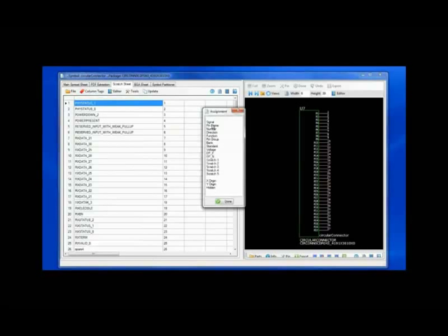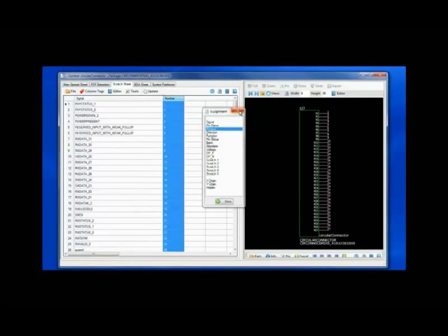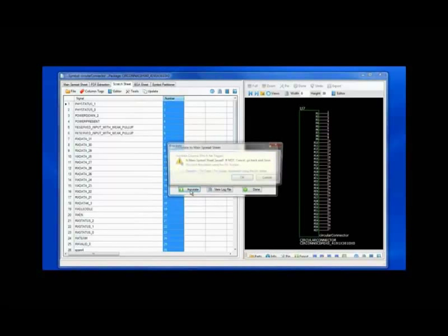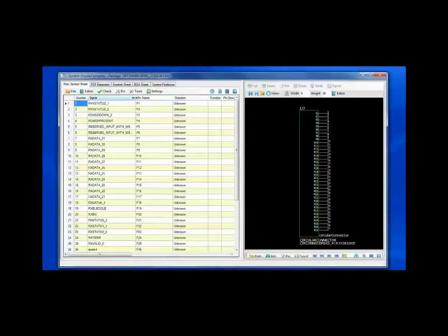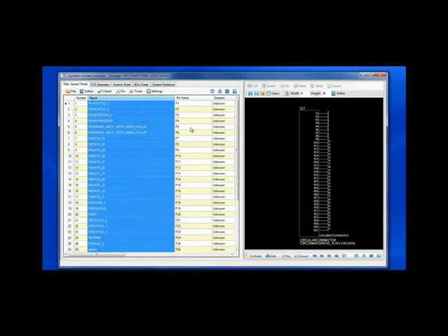And if we want to add more intelligent information, we can add it, such as the signal net names, the direction codes for modeling, to other downstream tools, and we can annotate that information from the Scratchpad spreadsheet to the symbol model. Going back to the main spreadsheet, you will now see the signal names, and if I had direction codes, they would be annotated.